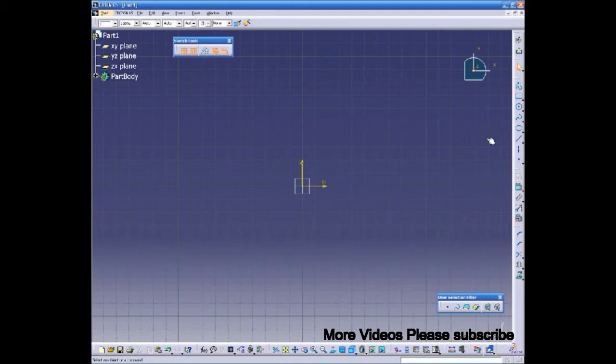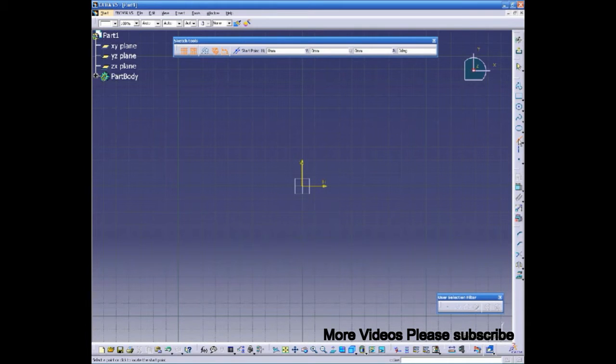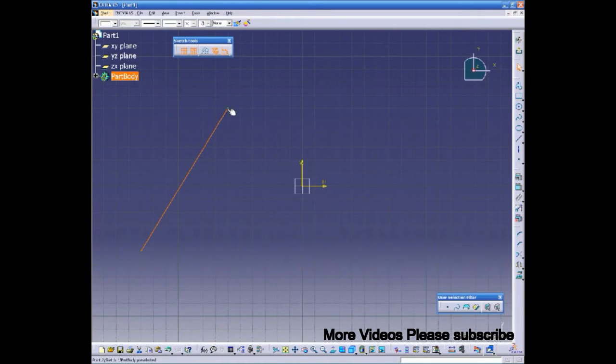Click the line icon. Click to indicate the first point in the geometry area. Then click to indicate the second point. The line is created. OK then. Let me go ahead with the line. I will show you how to create reference line this time.